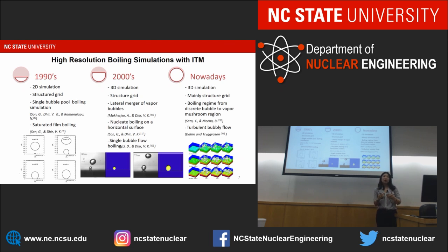Imagine that when you want to have a simulation with the subchannel spacer grid and the mixing vanes, how can you capture the sharp points in the end? That requires different skills, a different type of meshing, which is what we are using today: unstructured mesh.